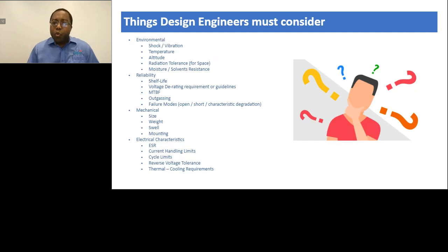I'm going to spend a few minutes stepping through some key parameters that must be considered when choosing a capacitor for Hi-Rel applications. In comparing all options, we must be mindful of how the capacitor performs, especially under varying conditions. Some applications expose capacitors to extreme environments, such as high shock and vibration, low or high temperature, radiation, and moisture. Capacitors not only must survive these various environments, but also need to minimize performance variation as these environments change.